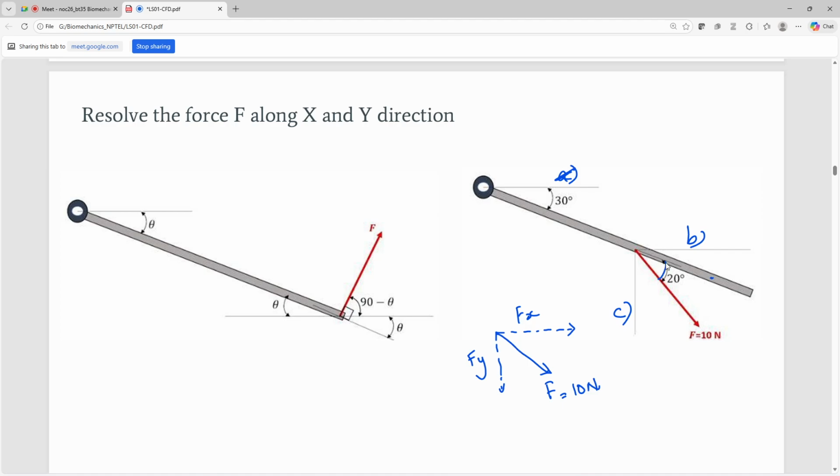So this is 20 degrees. So is this the theta of rotation with x or y? No, no. It is only the angle between the force vector F and the axis of the rod, but it is not the absolute angle with the horizontal or vertical.